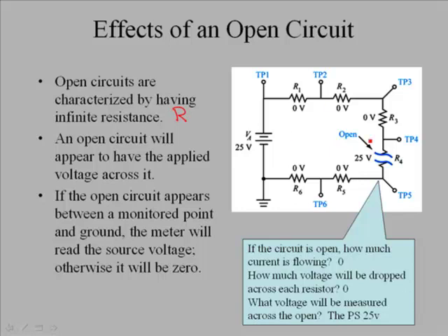In the circuit here, we have a component, and here we're showing a resistor, and the resistor is open. Commonly, what will cause this is that too much current has flowed through this circuit, and this particular component may have just disintegrated, burned up, and you look into your circuit and you simply see a charred component there. If you were to measure from test point 4 to test point 5 with an ohmmeter, you would commonly expect to see infinite resistance, because this component ceases to exist because it's simply burned up.